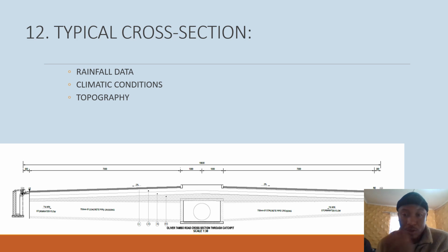And on the sides of our road, as can be seen over here, we had proposed to have at least the catch pits on either side of the road, and then have our stormwater cross our road back into the center of the road through a pipe that is proposed at the center of the road due to the cost limitations. And then we were going to have this water move into our pipe network and then go all the way into the daylight point.